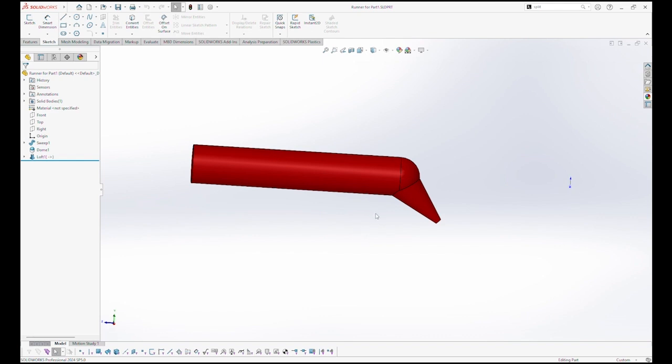There's also parting line gates, sometimes called tab gates. When your part does not have the ability to have a flat surface to put a subgate on, you can do a tab gate, but typically the runner and gate eject together with the part, and they're still connected. Then an operator would need to either twist the runner and gate to get them separated, which is an additional labor step, which is something most companies would charge you for,